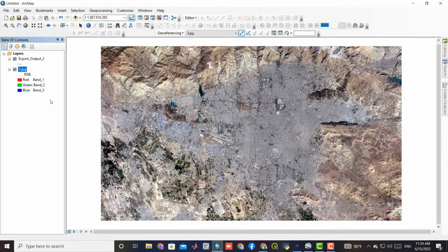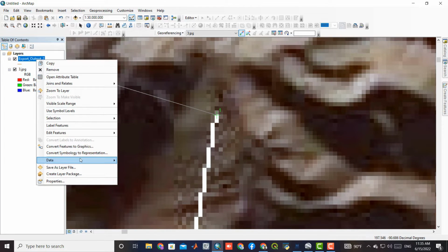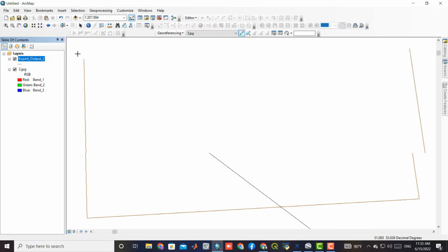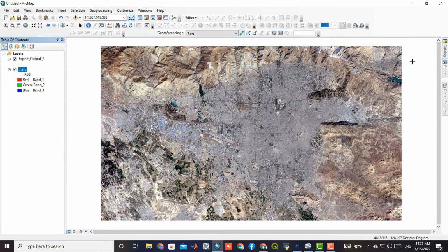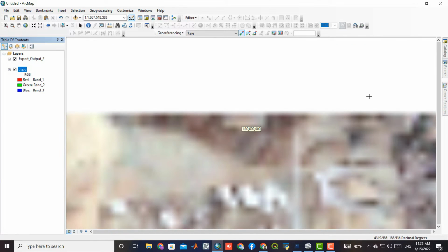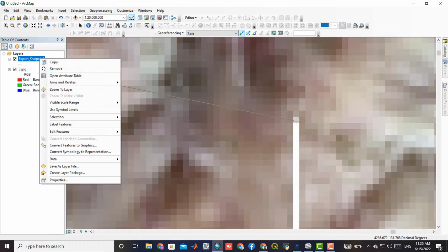Because it has no coordinates and is not georeferenced, it is not in the right place. The Georeferencing tool is a tool with which we can georeference images. Here we select the image and select the Add Control Points command. Click on the edge or the beginning of the drawn line on the image, and we go on the line shapefile and click on the exact same place from the line again, until these 2 points overlap. We go to the other side of the line and repeat the same steps again. We do all the directions of the line in the same way.